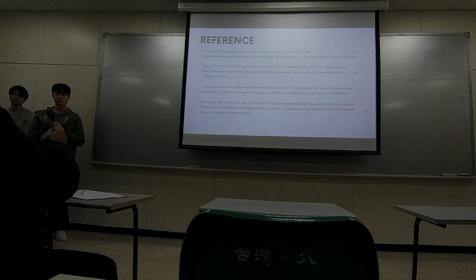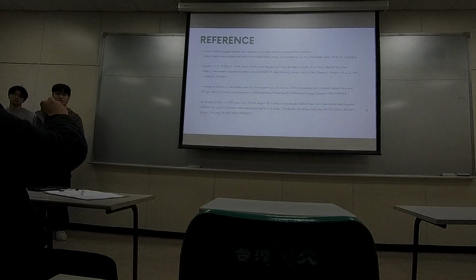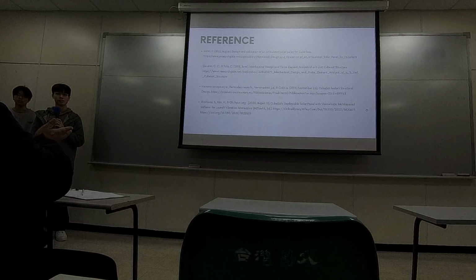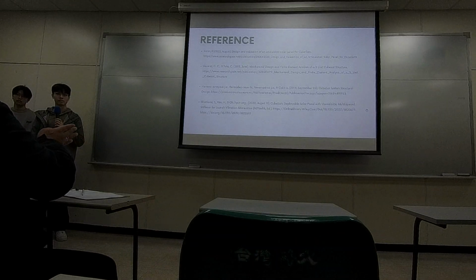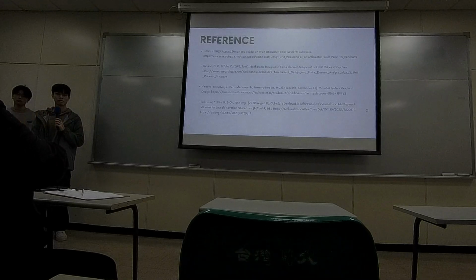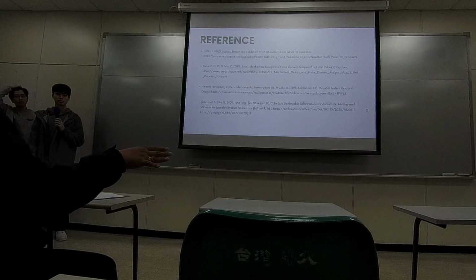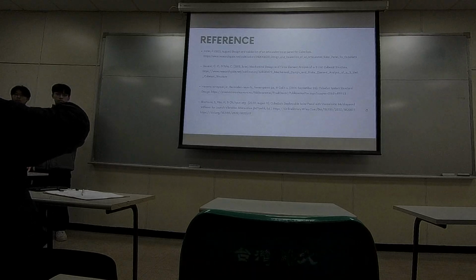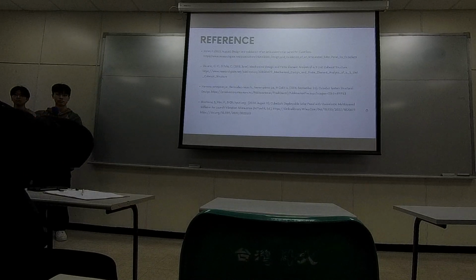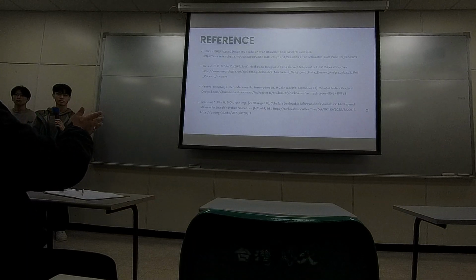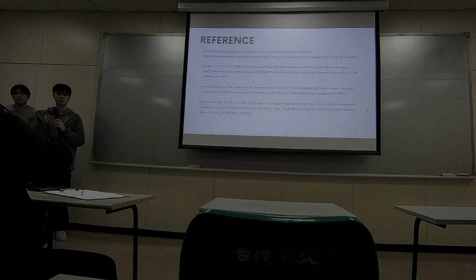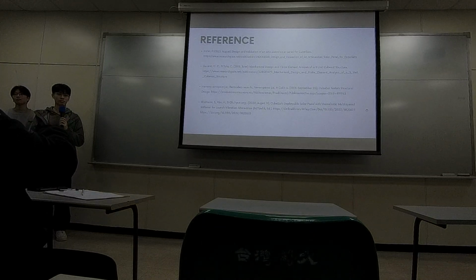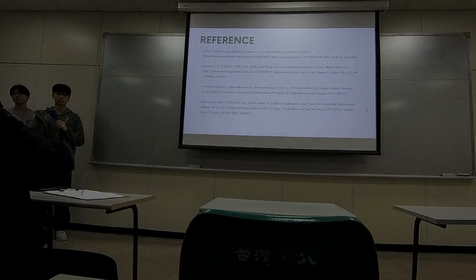Like there will be no actuator. You can try and compare that, because they are using actuators. But right now flexible solar panels are available. So just like a paper, you can fold it and just release the rod and it will automatically open. So no need for so many actuators, like in the mechanism you are showing, where you have so many actuators to open. To reduce these actuators, you can suggest something which is foldable and just opens. That's why the professor suggested in the beginning that you use some origami to open it.